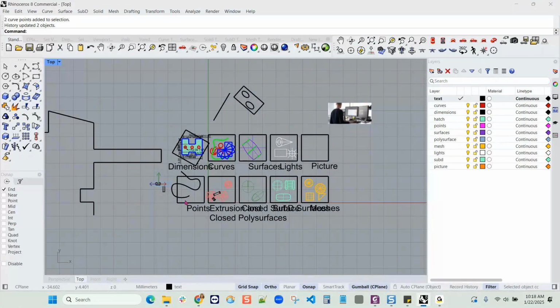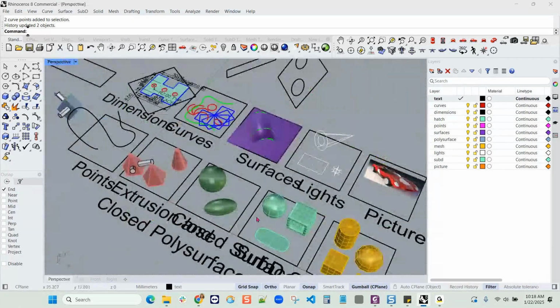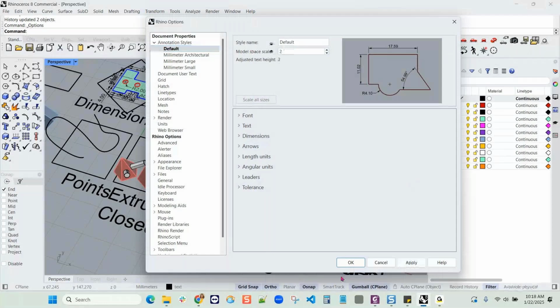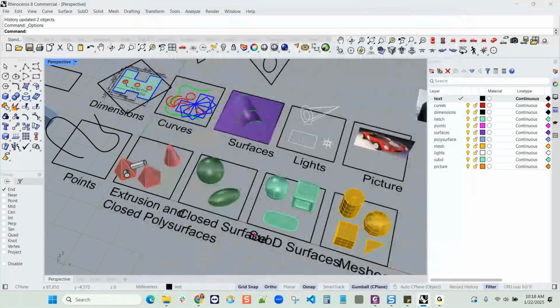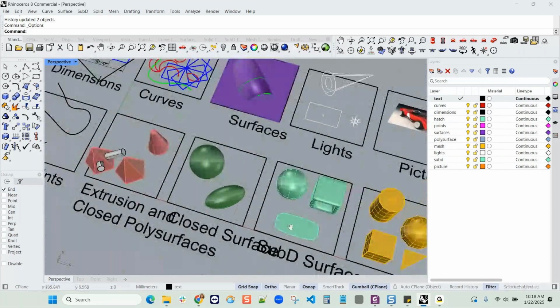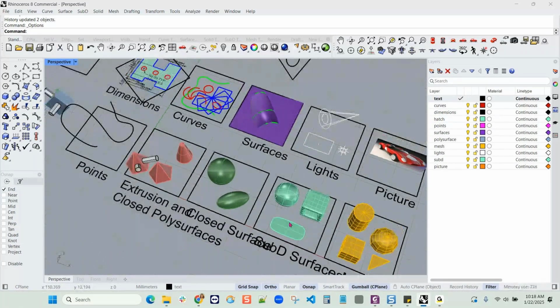Okay, there's some other specialty geometry here, and then we're going to go on. First, I want to go on to homework. And what I did here when I changed default to 3, the text actually got bigger too, so I can bring that back to what it was. I could change them to a different style so they're not affected by that default dimension style, and that can happen very quickly by using cell text.